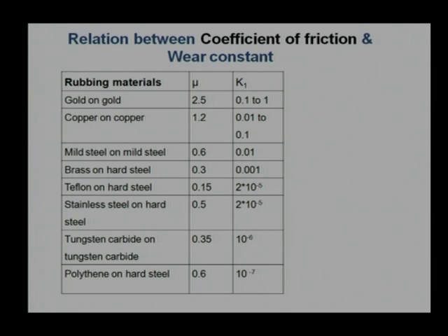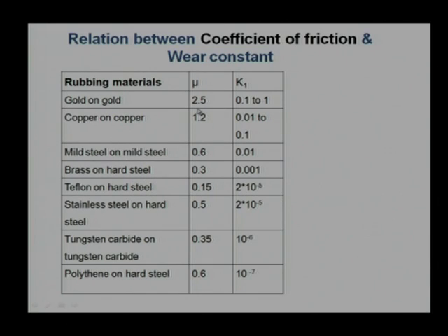We have expressed adhesion friction, the friction due to the adhesion process. We have given a relation for the wear rate due to adhesion. So, there is a possibility of some relation between the coefficient of friction and the wear constant. Some studies show there is a strong correlation, and some studies show there is not much relation, they are not related at all.